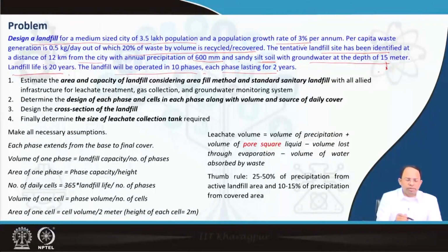So what do we have to estimate? We have to estimate the area and capacity of the landfill considering the area fill method and a standard sanitary landfill with all allied infrastructure for leachate treatment, gas collection, groundwater monitoring system. Determine the design of each phase and cells in each phase along with the volume and surface and the source of daily cover.